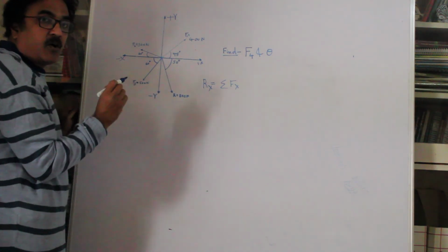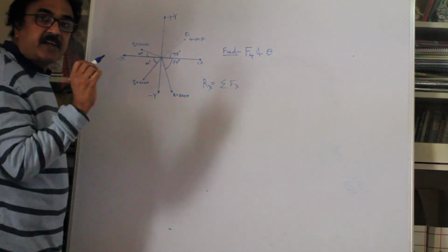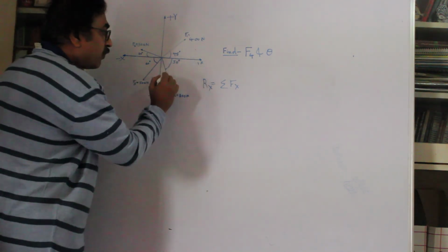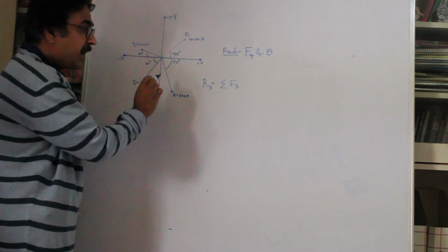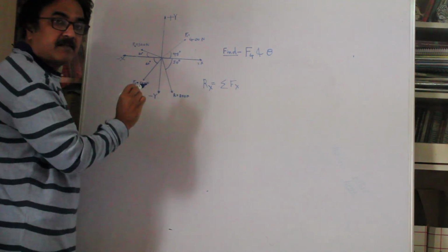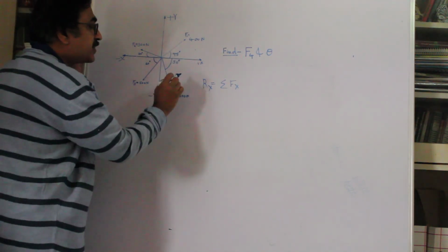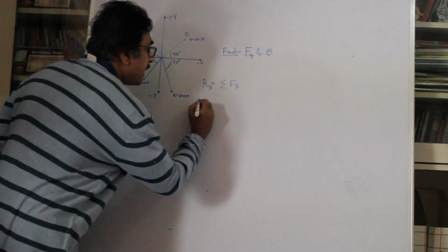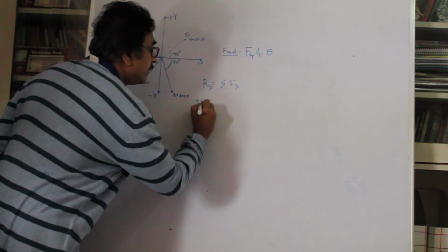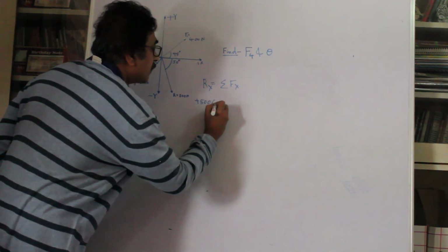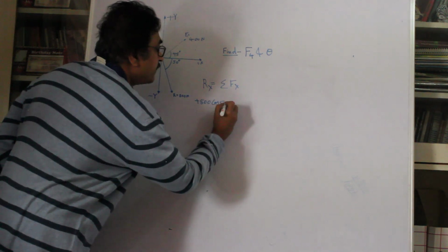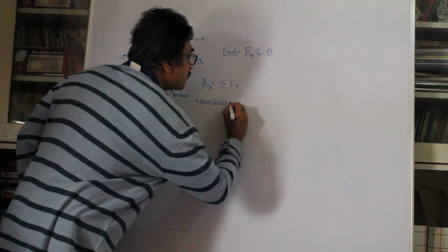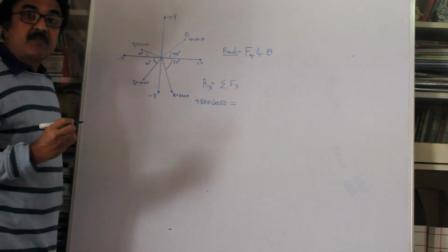Right? We know that the horizontal component is cos of the angle which the force makes with the x-axis. This is in the 4th quadrant, the resultant R, and in the 4th quadrant the x-axis is positive, and after resolution R is also along x-axis, it's going to be positive. So I can write it as plus 800 cos 50. This is the resolution of R along x-axis, and this has to be equated to sigma Fx.